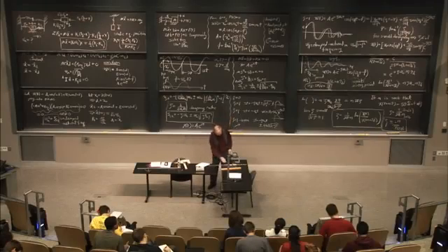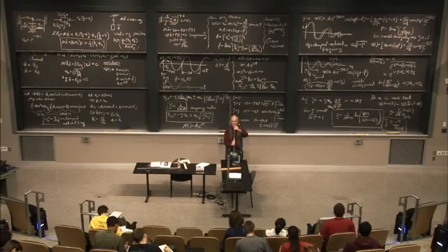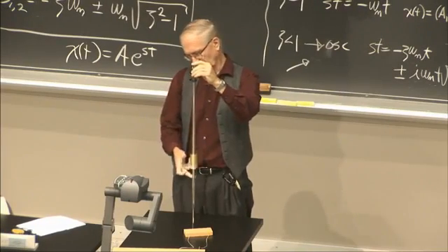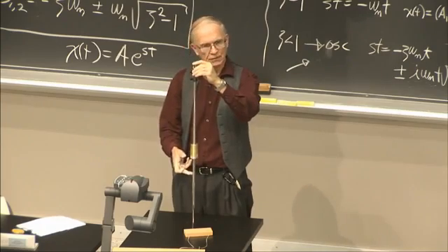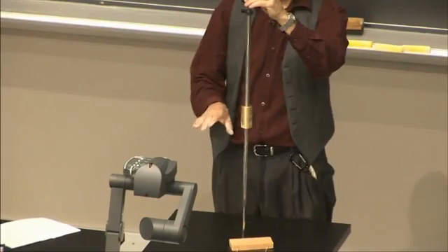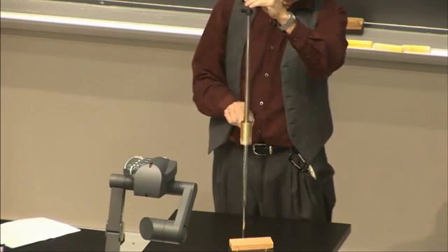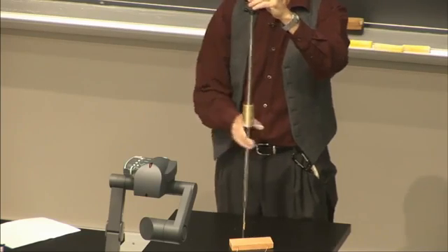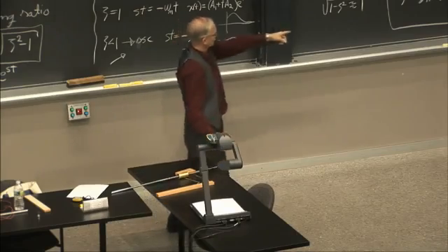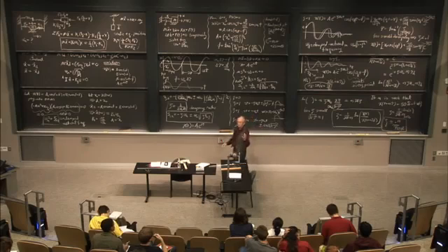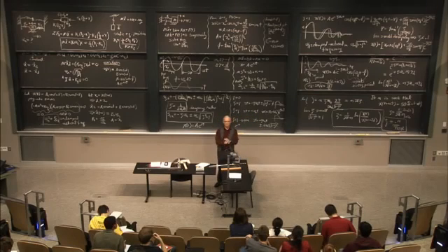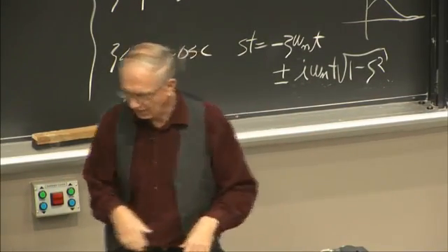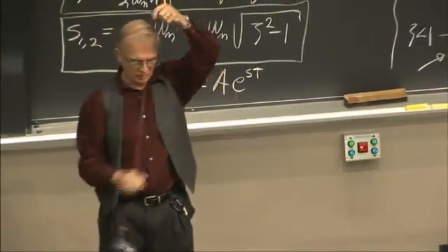So if I have an oscillator, I can do an experiment, give it an initial deflection, and say, you know, it starts off at 6 inches or 3 inches amplitude, and you let it oscillate until you see it die down to half of that value. So let's say 1, 2, about 4 cycles, this thing decays by about 50%. Okay? 4 cycles. Plug 4 into that formula, you get about 0.025. Agree? 2.5% damping. Really very convenient little thing to carry around with you. Measure a pendulum, how much damping does it have?